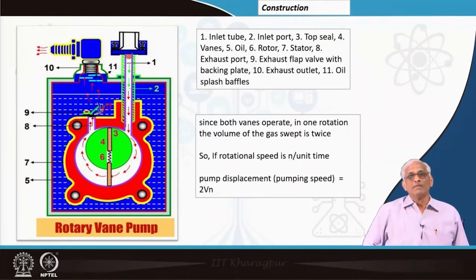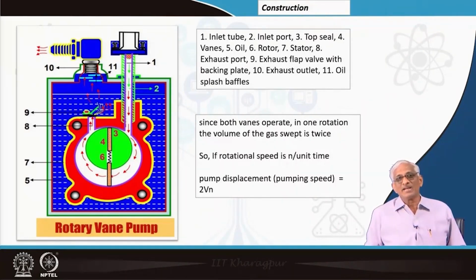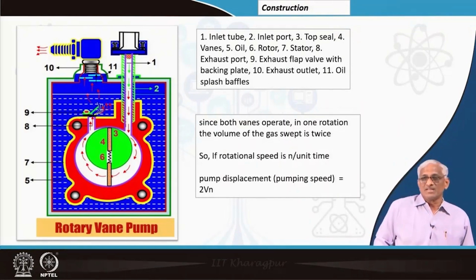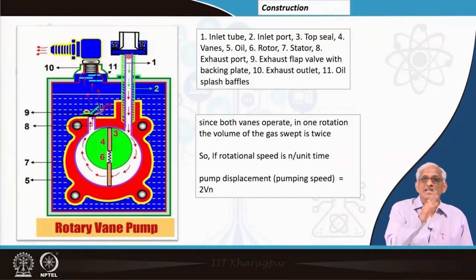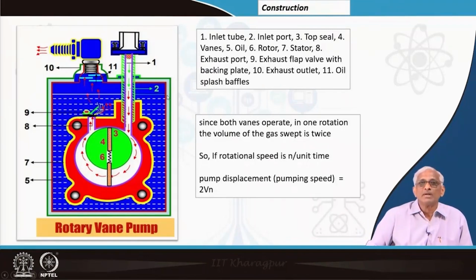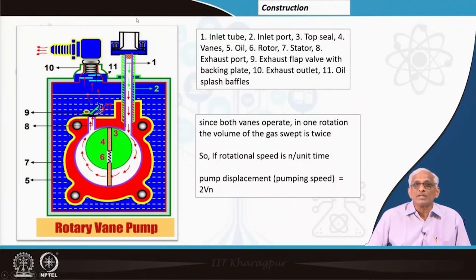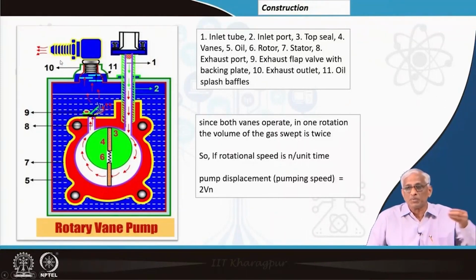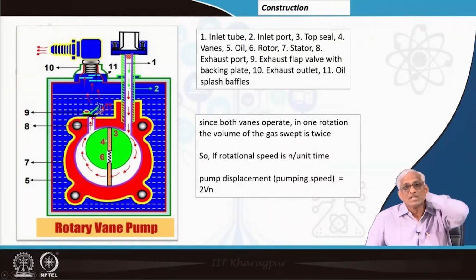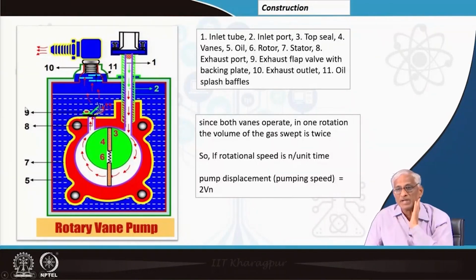Then, if you carefully observe, there is one inlet and one exhaust, on either side of the top seal. The entire chamber is submerged in an oil container, and this interconnecting pipe, the inlet hose, is connected to the chamber to be evacuated, and the exhaust is to be connected to the open air, if it is allowed. Otherwise you connect it through a pipe and take it out through the window, otherwise some oil vapors may come out into the room and cause a smell.